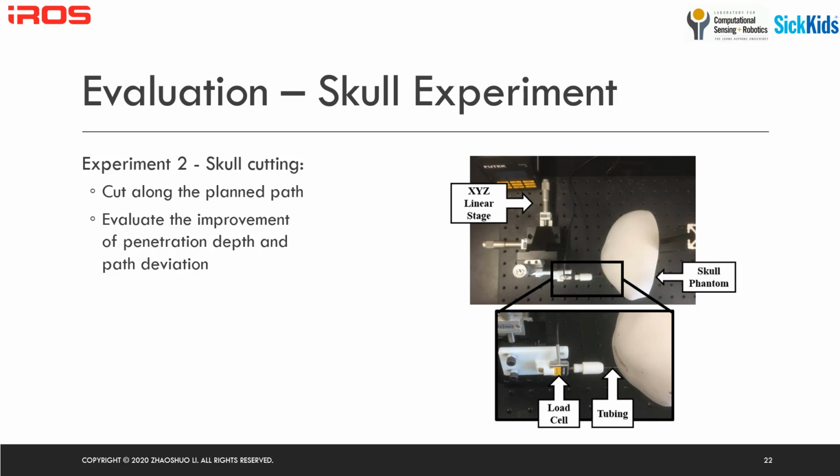The penetration depth is measured as the offset between the exterior of the skull and the wax. We use an XYZ linear stage with a load cell mounted on it. A small tubing is installed on the load cell to detect contact. Therefore, we are able to measure distance.